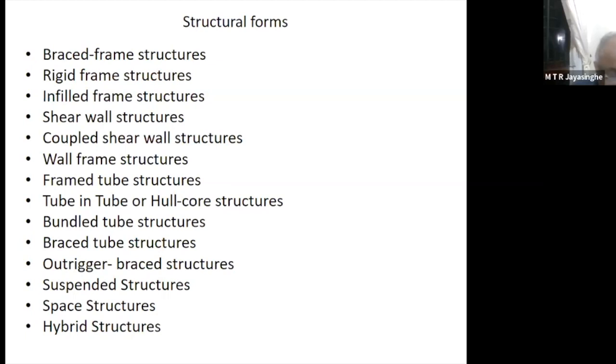And if you go to our ISL own building, the steel building is already showing signs of corrosion, which is not a good indicator. Always keep in mind, any deck material that you use out of steel must be out of the best, well-protected steel, so that it's not going to corrode. Because corrosion of a slab in a tall building is a disaster. So you have to be very careful when you are using all the different systems. Then there is the next one.